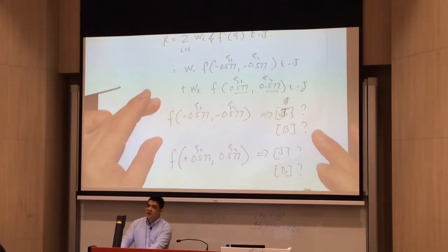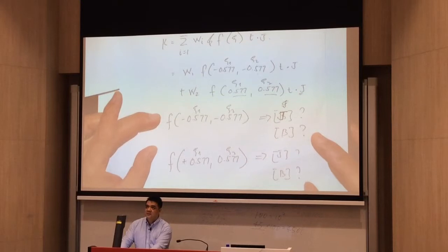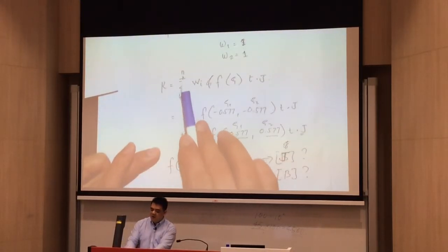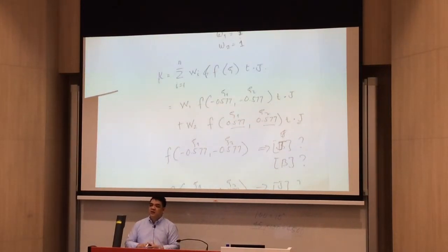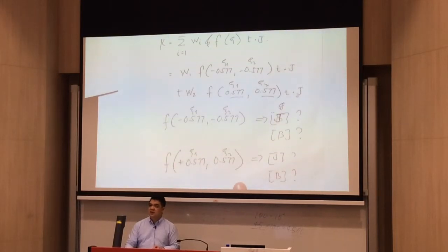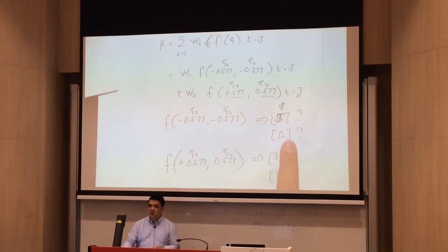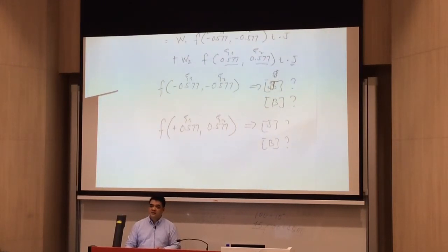So this one is numerical integration. You don't need to really integrate this one. The more number of Gaussian points that you use, the more accurate your solution will be, but the more calculation time. Because you need to determine your Jacobian for these 2 points and your strain displacement matrix using these 2 points.